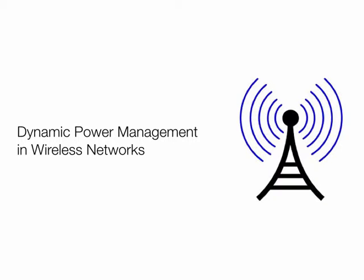To summarize, on the Ethernet side, scaling didn't work, even though that seemed very promising. What now exists is this simple scheme. You're idle, with some sort of idle time policy. You bring both sides of the link to a low power state, but you keep sending this refresh message, and then when you want to bring it up, you rapidly bring it up.